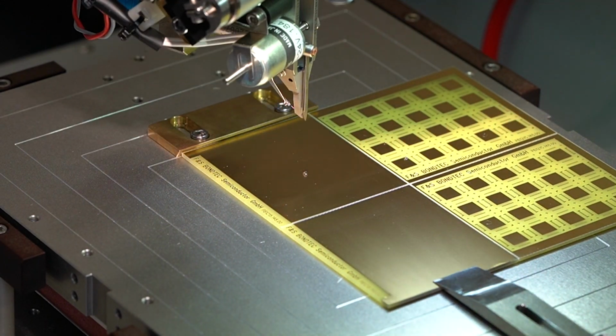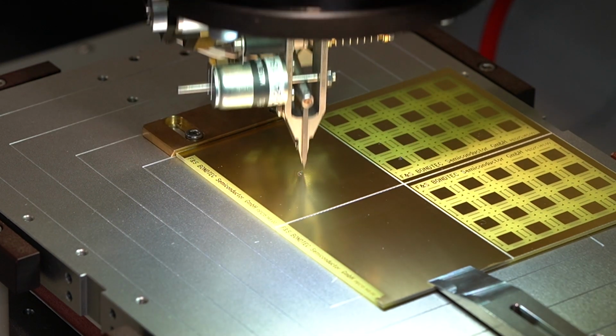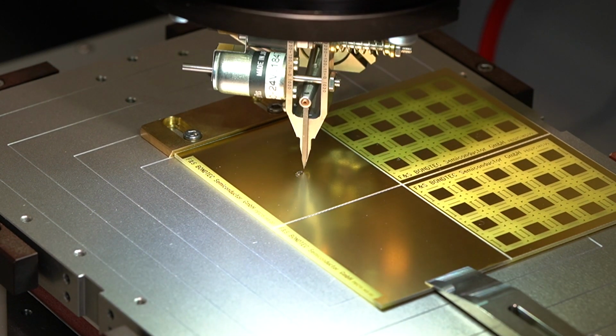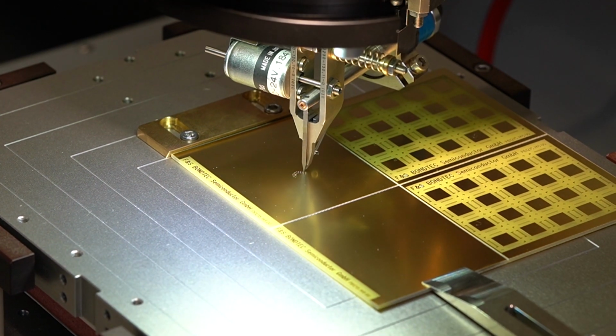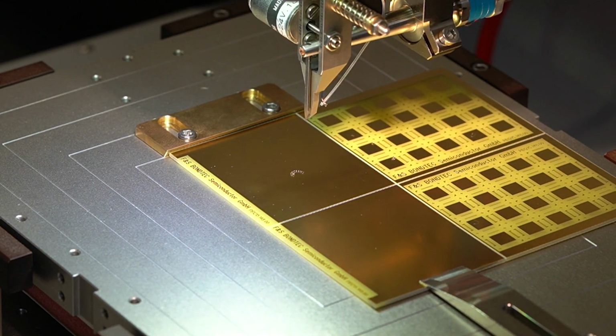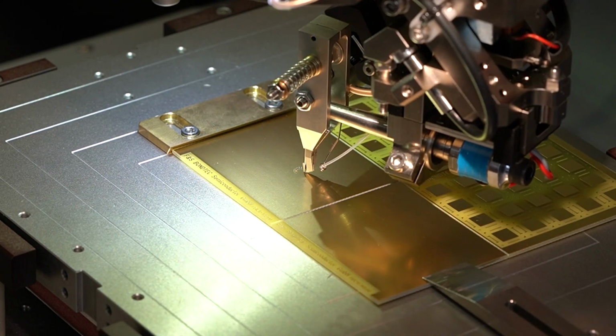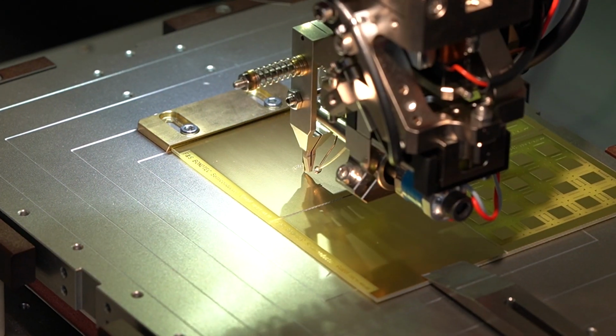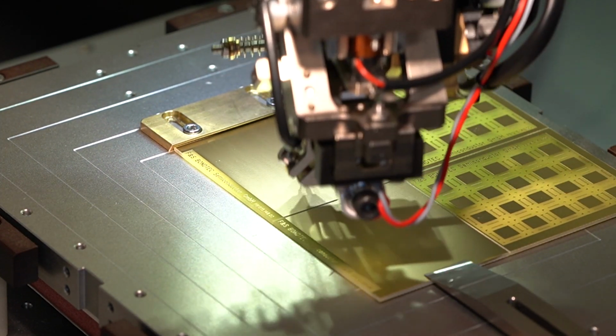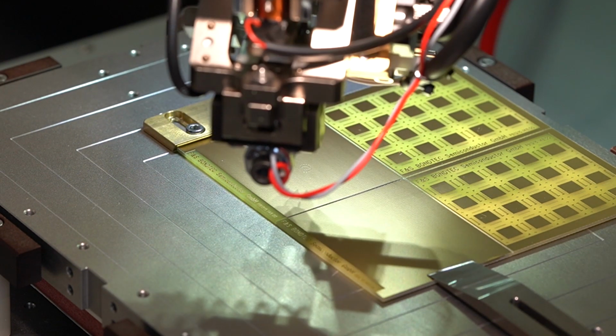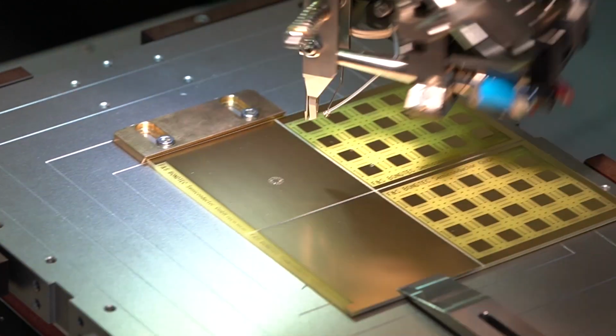Their length and spacing can be chosen at will. In our case, around a circle of 1.1 mm diameter and with a loop length of 1 mm. The bonder then makes an automatic run with these bond wires. Once all the bonds are made, the operator locates their positions using the camera.